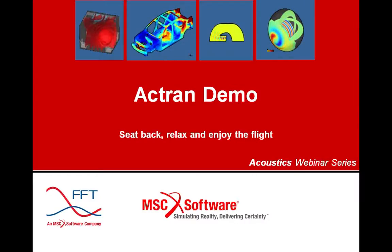Okay, now what I propose is to guide you through the graphical interface during a live demo. In this demo, we will again look at the radiation of a gearbox. The vibration level has been computed with Nastran, and I will first show you how to set up an Actran model based on an existing finite element mesh, and then we will do the post-processing of the acoustic results.